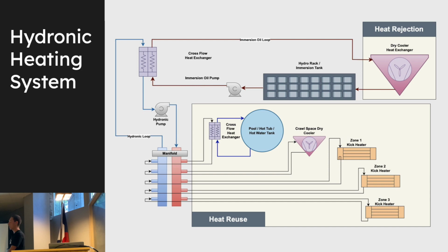You don't always need glycol. Glycol is an antifreeze. It's in your car radiator. If you're in a cold climate, you'd want glycol so the water literally doesn't freeze in the pipes when you're not running it. That transfers down to a manifold, and then off the manifold you can just tap off in different lines. Let's send it to all these different places.